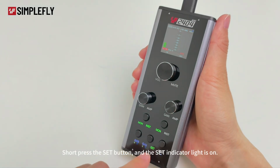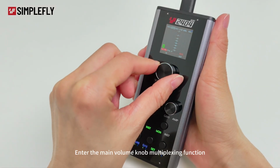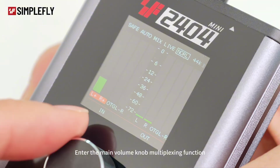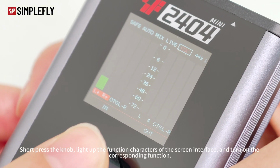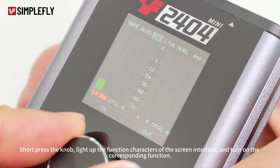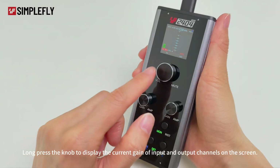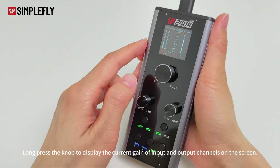Short press the SET button and the SET indicator light is on, entering the main volume knob multiplexing function. Rotate the knob to select the screen interface function. Short press the knob to light up the function characters of the screen interface and turn on the corresponding function. Long press the knob to display the current gain of input and output channels on the screen.